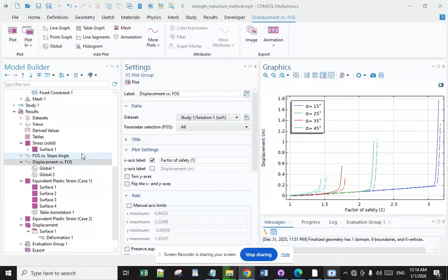Risk analysis, failure mode and effects analysis, and other tools are commonly used. Design factors for specific applications are often mandated by law, policy, or industry standards. Buildings commonly use a factor of safety of 2 for each structural member. The value for buildings is relatively low because the loads are well understood and most structures are redundant.